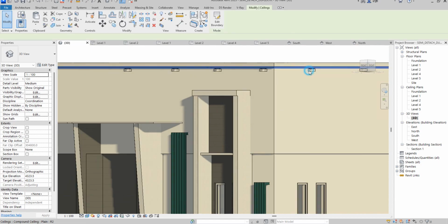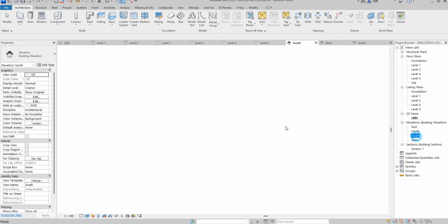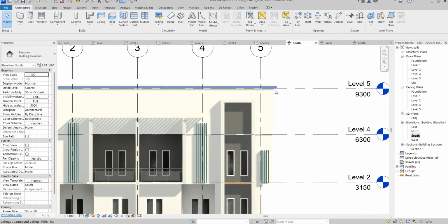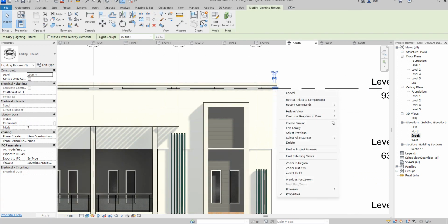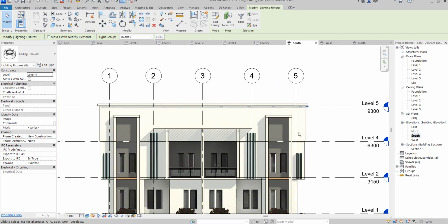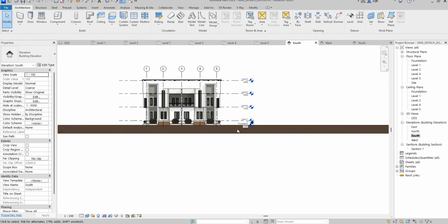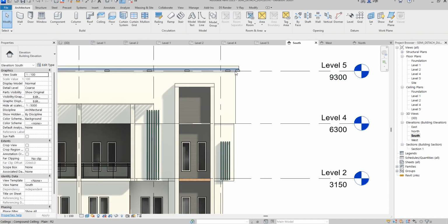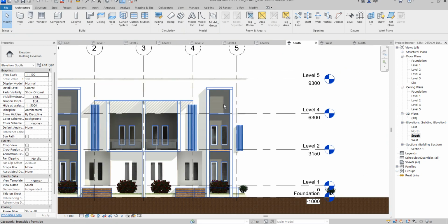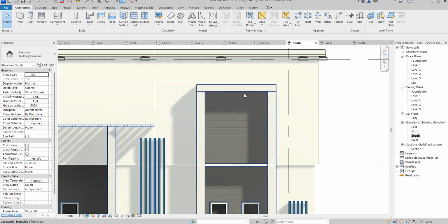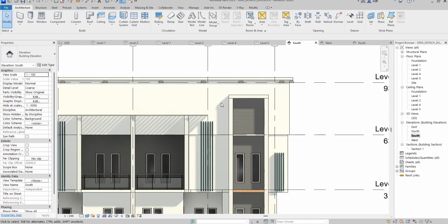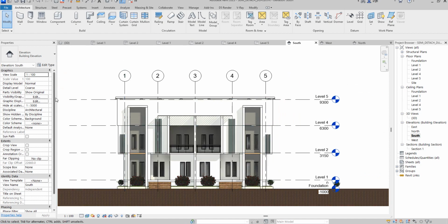So you just need to select now, go to start elevation, select all instances at this level, so you'll be able to mirror them. Select all instances, and you just say mirror. So mirror as we always have it, and you stick to it. So that is how you select mirror and create ceiling light on that one. You can as well add those ceiling lights to this one, but I'm not going to use this one. I'm going to use wall lighting for this one.